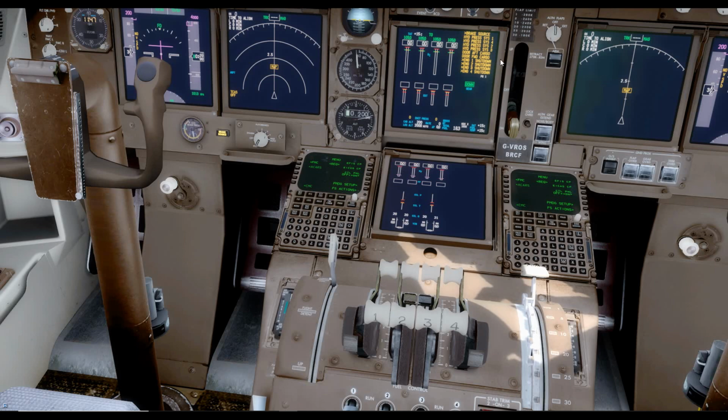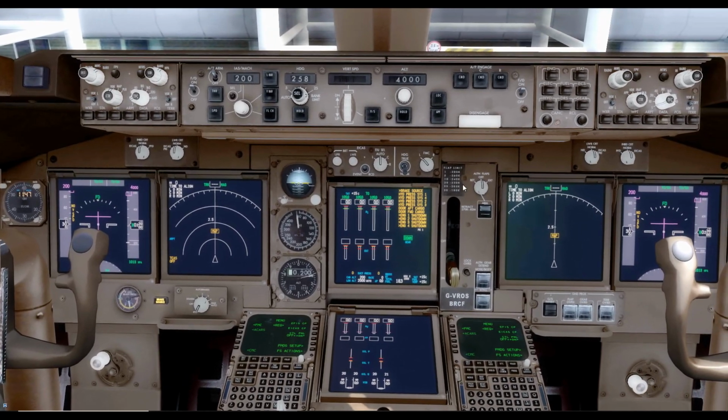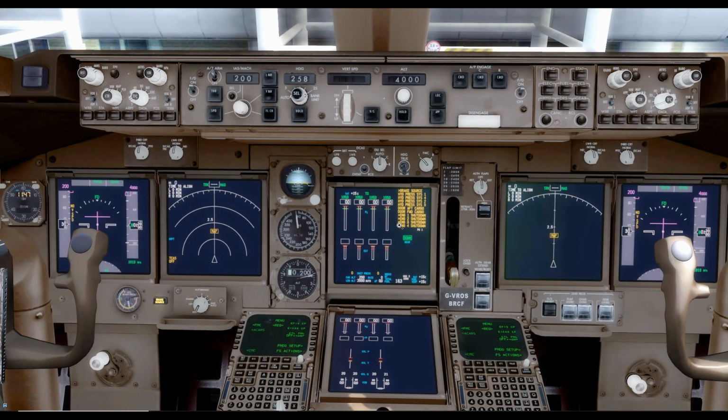To see if the legend is shown on the ICAS screen, we can cancel some of the alerts that we have here on the upper ICAS, and we're checking them, making sure there are no alerts at this stage that we weren't expecting. You can see on the upper ICAS that we have more than one page of alerts at this stage, and this is perfectly normal.